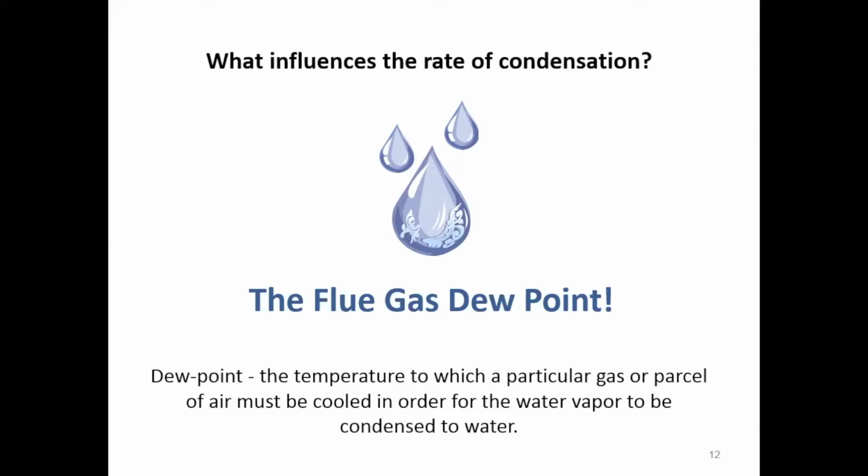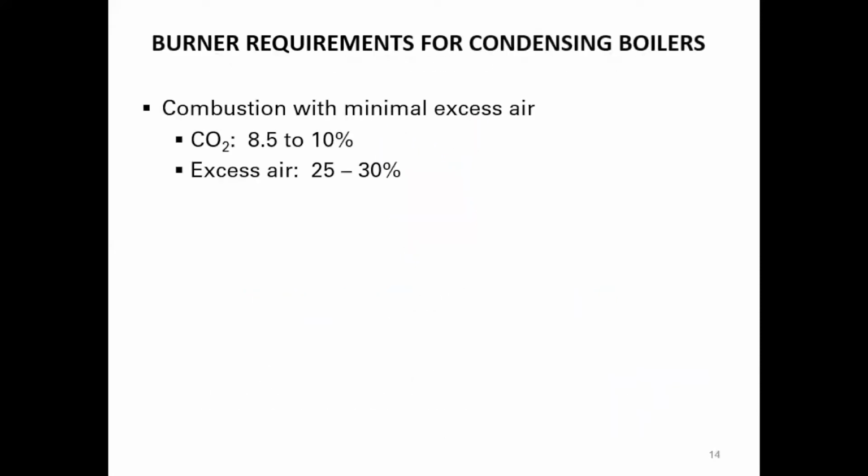Now, the thing with the flue gas dew point, it's not a set number. It's actually tied to the combustion process. So in the class about combustion, we talked quite a bit about the combustion process itself, but trying to keep it down to, say, one slide about combustion. Okay. If I want to control my losses and control my dew point, I should have combustion with minimal excess